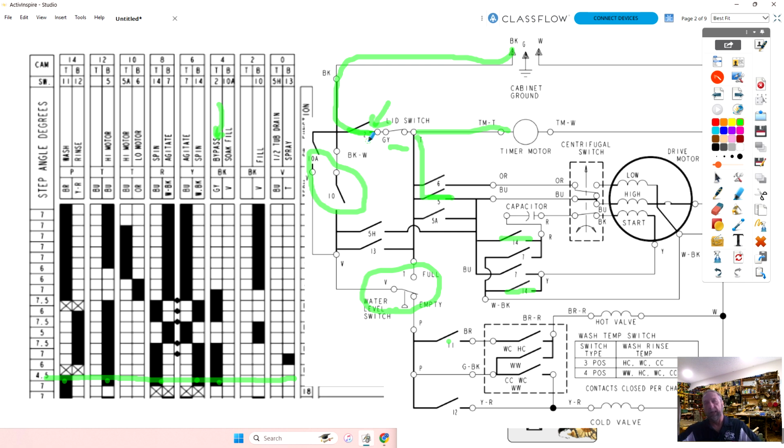But in a locking mechanism, we have wax motors on some manufacturers. On the old Neptune front load washers, they had a resistor on the board, and it was always burning out those wax motor mechanisms. A wax motor is very similar on the Frigidaires and the old Neptune washers, but on a lot of the newer machines, when you put a Whirlpool top load or front load washer into a cycle, if it's a wax motor, you don't hear it.